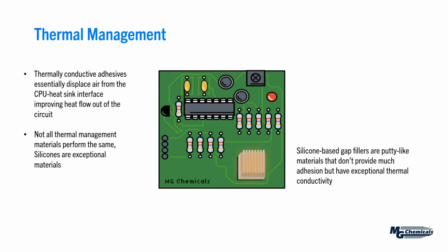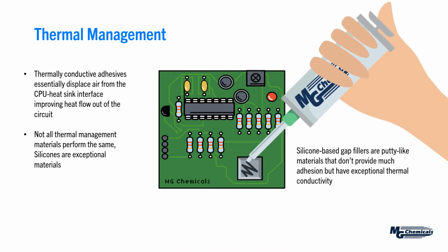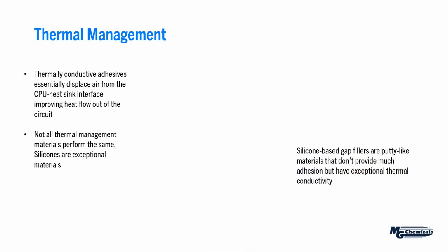So with traditional materials, you will get reasonable thermal conductivity. But with silicone materials, what you tend to get is a much higher degree. And that's what I'm trying to show here when the heatsink sort of glows red. That's meant to show that that heatsink is getting hot, so the adhesive is more efficient as a thermal conductor. And that's true if you compare thermal conductivity values.